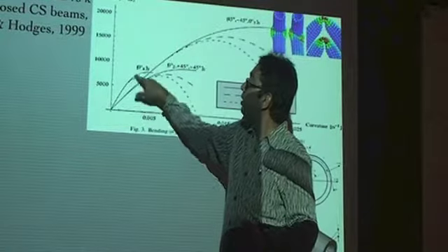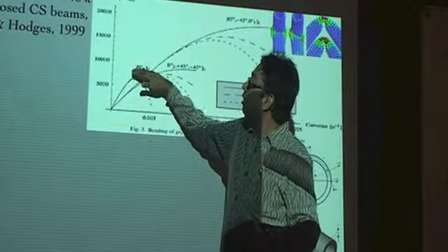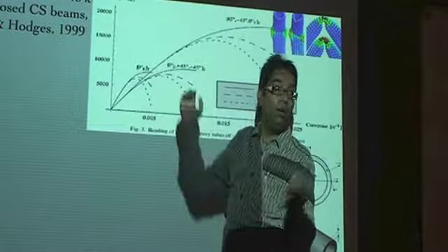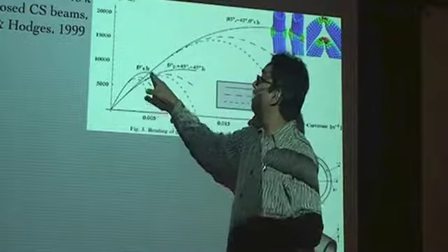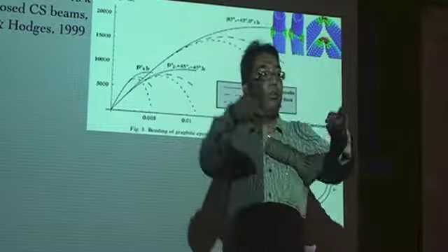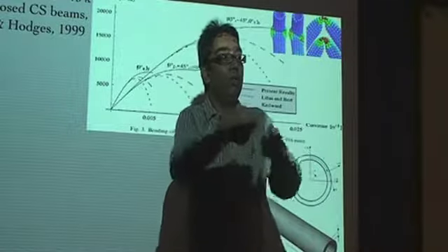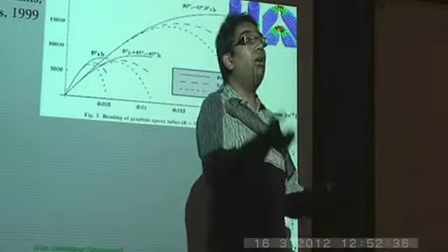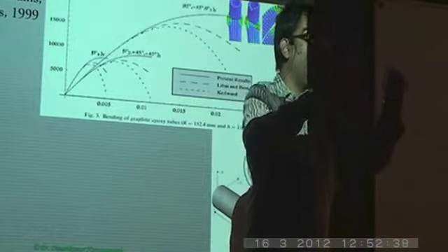In other words, after a certain value of moment, even without increasing the value of the moment or the value of your bending loads, you're basically seeing a rapid change in curvature. And that's the example of the drinking straw that we are talking about. As soon as you, or there might be local buckling which is taking place.